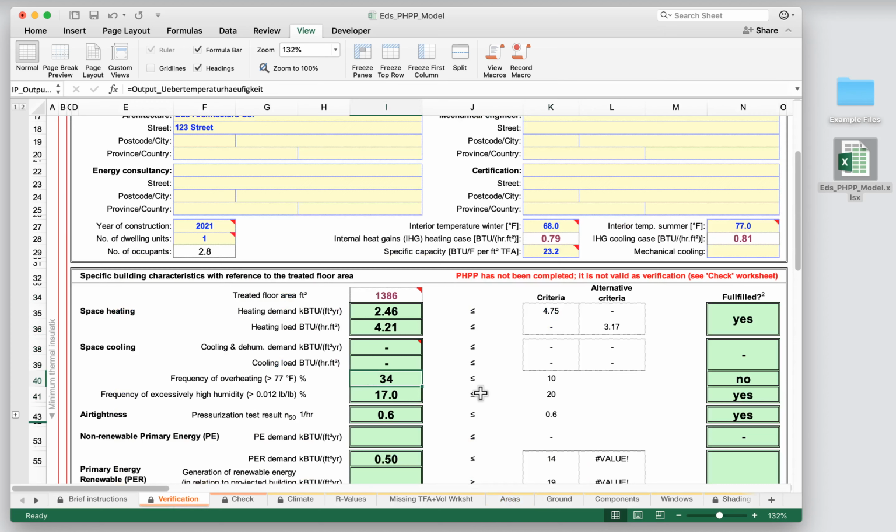Not a whit. Okay, so with our R40 walls, such highly insulated walls, going from 0.6 to 0.4 doesn't really amount to much change at all. All right, so that didn't really help us at all. In some other circumstances, maybe it would, but in this case, it did not do anything for us. So that didn't really change our value there at all. So what else could we do?